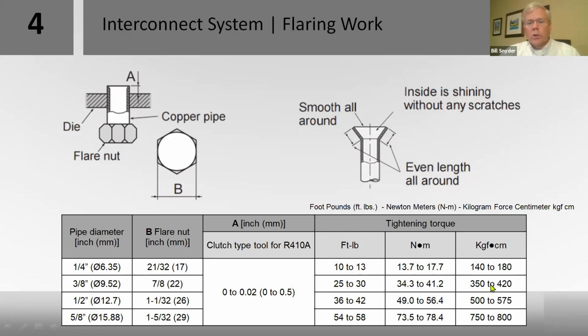Don't use this chart as gospel. Use the one that comes with the equipment, because some of the torque is different on some of the equipment than others. Even though it's a 1/4 inch or 3/8, the torque can be different from one piece of equipment to the next. And the reason we want you to torque it is not so that you get it tight enough, it's that we don't want you to over tighten it. If you over tighten the flare, you can actually crack or flatten out the flare and do more damage. So a 1/4 inch fitting doesn't take that much torque.